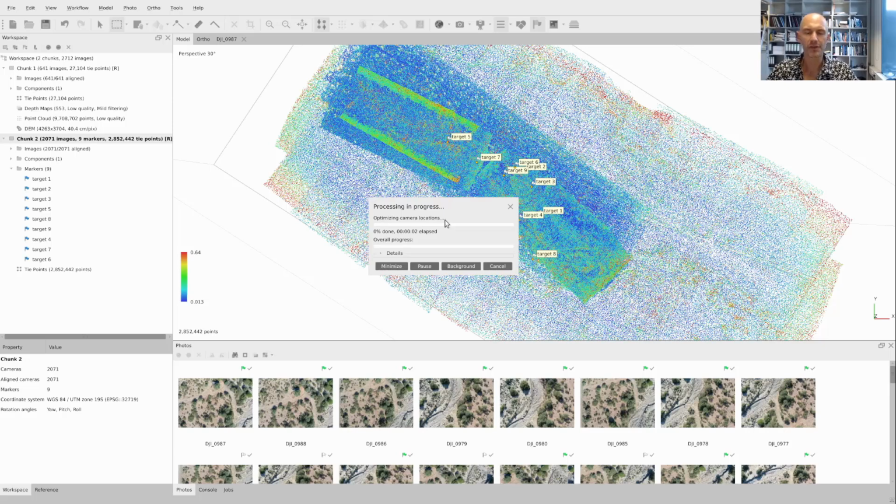Because we have removed some points or some cameras, we are going to have a subset of these, but you can still see that the area of interest is very densely covered here. Because we have removed those points, it is generally advisable to rerun the optimization process, because now those points are not in the matrix that is being solved, so you end up getting a much more accurate result. And then we continue with the filtering.